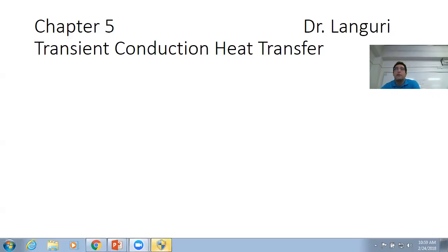For example, if we assume the wall behind us in the classroom, with one side facing the air outside and the other side facing the air inside the room, then for a short limited time, we can assume the temperature on each side is fairly constant. So this is a steady state. The temperature or the condition on the boundary doesn't change with time for a limited time.